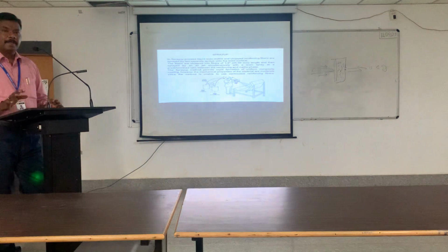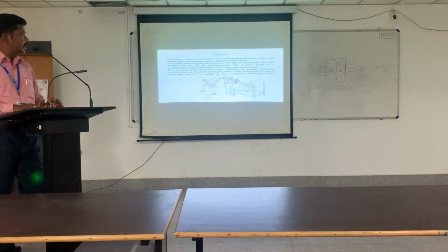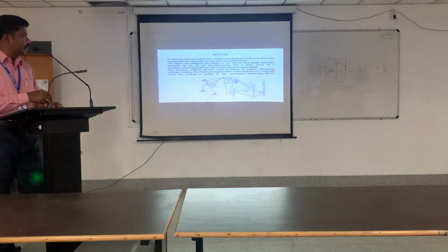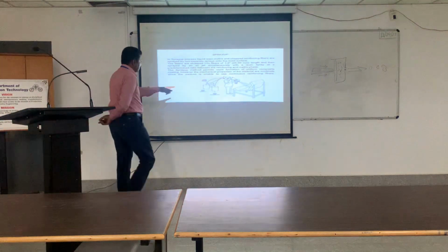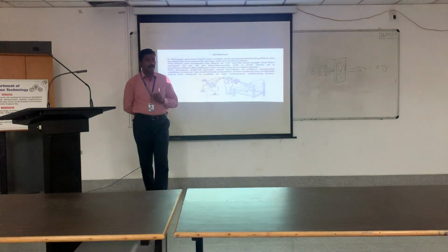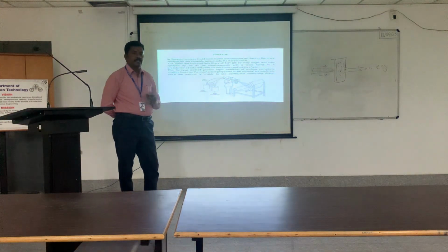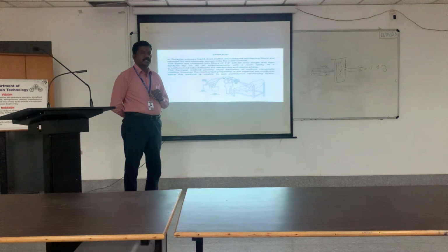This depends on the curing nature of the matrix material. The matrix materials can be taken in one tank, and the fiber will be taken on another rack. So this is the fiber rack, and these two are the matrix materials. This is a resin, the matrix, with the catalyst, and resin with accelerator. Maybe you would have studied about the catalyst and accelerator in your schooling or undergraduate itself. What is the difference between these two? What is the purpose of these two? Catalyst and the accelerator.